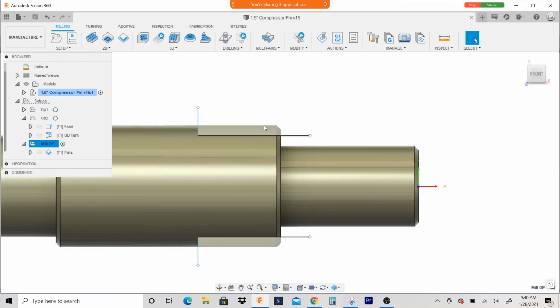And the reason why I did that was, you're using a 1/2 inch end mill, okay? So you have to think the toolpaths are driven based off the center of that end mill. So anytime the software does any kind of compensation of an end mill, it's compensating the radius. So if you're using a 1/2 inch end mill, your radius is going to be 0.25, right?